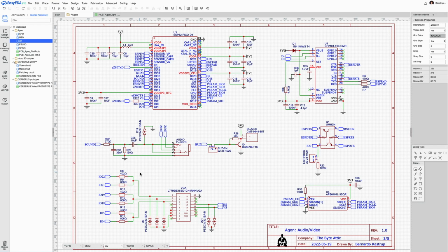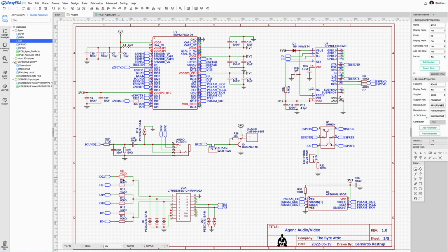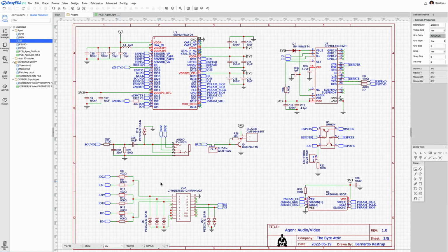And from the minimum level of that color, not brightness level, the minimum level of that color, you should get a very, very low value, very close to 0 volts. It so happens that I found resistors with almost the exact value that comes out of the calculations. They are not common, but there was a lot of stock available for these strange values. So I decided to use the strange values and not sacrifice color accuracy just to use more common values, because yeah, this stuff is made. At least in China at LCSC, there was a lot of stock of these resistors.